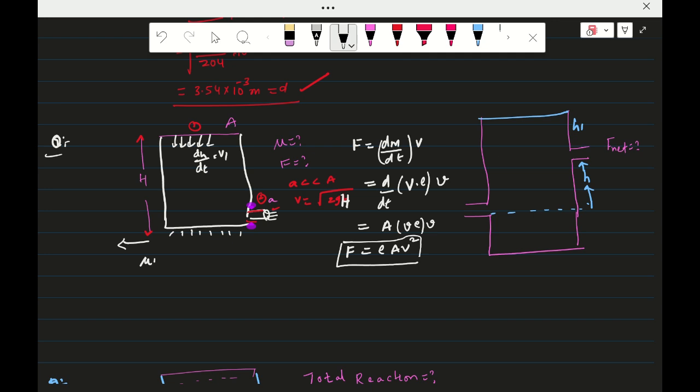if there is friction, that is equal to mu mg equals rho A v square. Here again m is the total mass of the liquid, that is equal to A into h into density into g, so mu times that equals rho A v square. Rho A and rho A get cancelled. Then v is equal to root over mu into hg. So this is one formula.